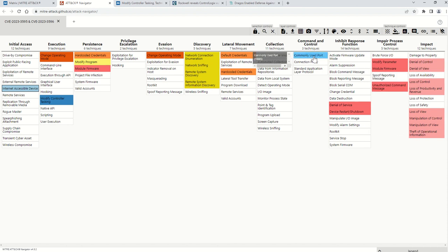And using the common ports that are used in the CIP protocol, that is 2222 and 44818, it can send command and control information to these PLCs, to these devices, and then further create an impact. So one mitigation technique is that you can block ports 2222 and 44818, which are used for this Common Industrial Protocol, on your firewall from the IT networks and from the internet.